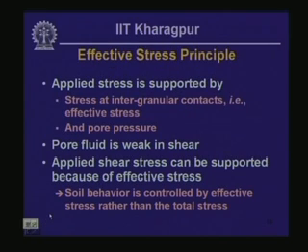Okay. Now we look at the effective stress principle. Applied stress on a skeleton of soil or rock, saturated skeleton of soil and rock, is supported by stress at intergranular contacts and pore water pressure, as we have seen already. Now since pore fluid is weak in shear, if we apply shear stress to the specimen, then it can only be supported because of effective stress.